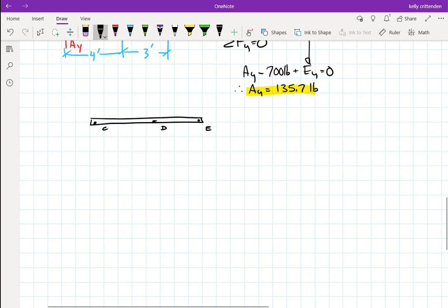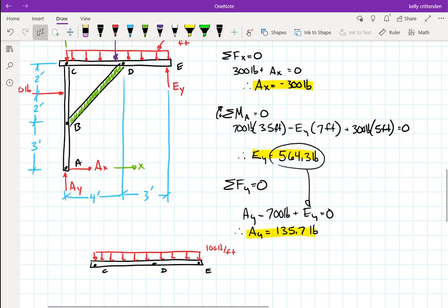So we have that distributed load. Now I'm going to redistribute it instead of having a point load, although we are going to probably do some more equations like moments or forces in X or Y, and you probably do want to re-lump it into the 700 pounds, but for now we'll leave it like this. At C, we have member ABC connected. Neither of those are two force members, so we're just going to have to put CX and CY.